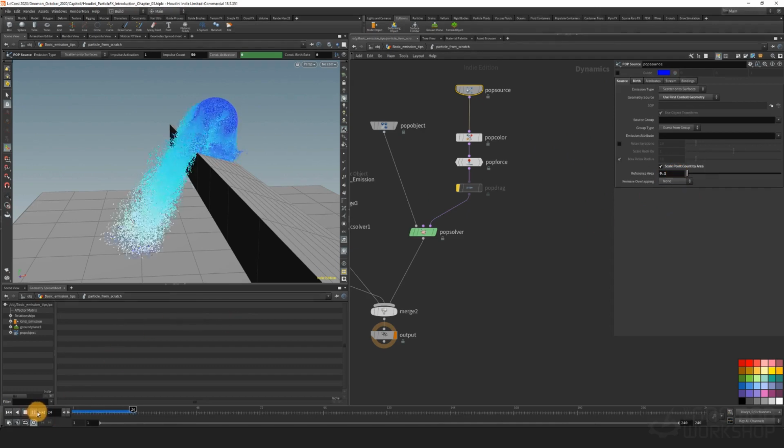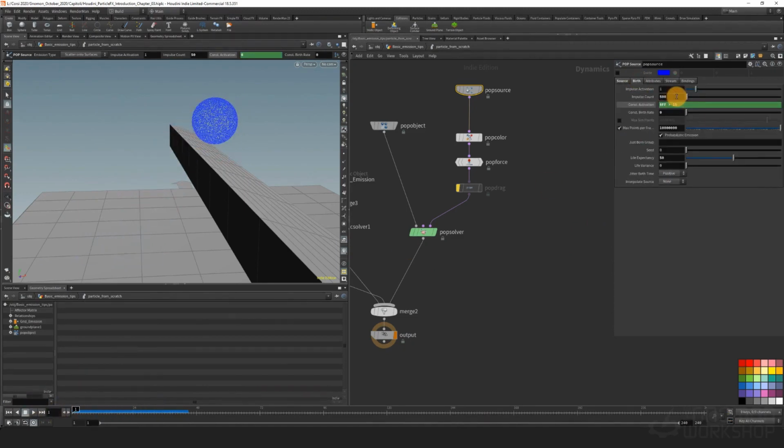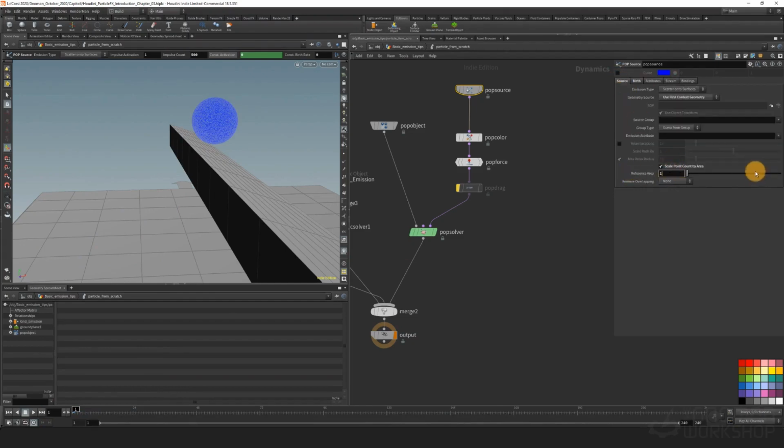And you see that if we go down there, we have the possibility to have more and more particles just based on the area. So if we say there that we have 500 particles by impulse, and then we use this one, if we say 1, we are using the same value. If we say 2, we are losing the amount, okay? But if we go lower, we'll have more and more particles. So we are scaling how many particles are generated just using this value.